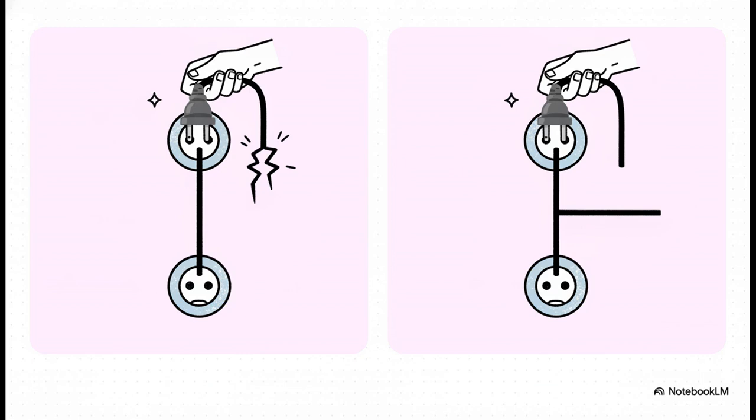In a full normal setup, the top output socket connects to the bottom input automatically, no front cables needed. But if you plug a cable into either socket, that automatic connection breaks instantly. Now, in a half-normal setup, plugging a cable into the top output does not break the connection. It's kind of like a Y-splitter cable. It lets the audio keep flowing down to its normal destination while letting you bleed off a perfect copy to send somewhere else entirely. Pretty smart, right?